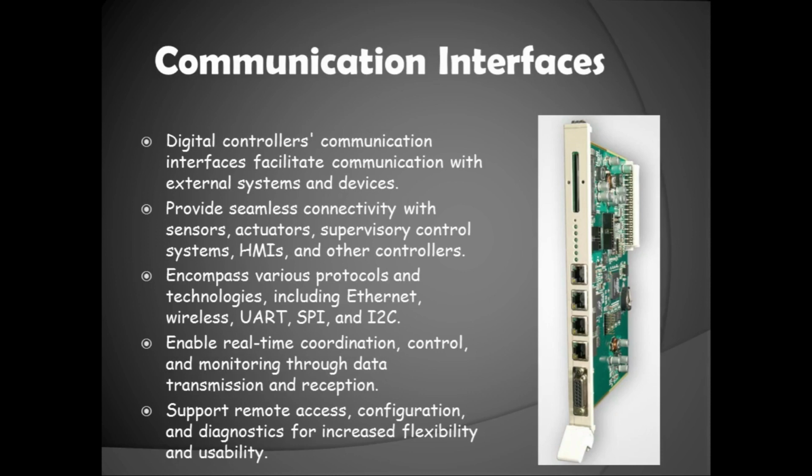Communication interfaces. Digital controllers' communication interfaces act as the entry point for communicating with other systems and devices outside of the controller. These interfaces provide for seamless connectivity and efficient communication between the controller and other components, including sensors, actuators, supervisory control systems, human-machine interfaces, and even other controllers. The term communication interface refers to a range of protocols and technologies, including modern networking techniques like Ethernet or wireless connections, as well as serial communication standards like UART, SPI, or I2C.